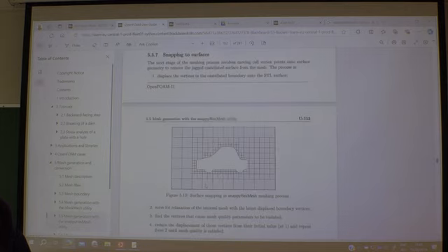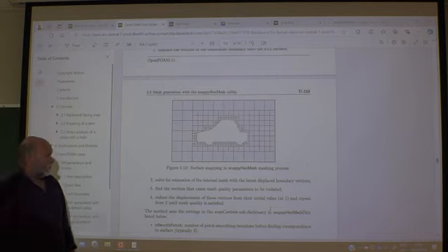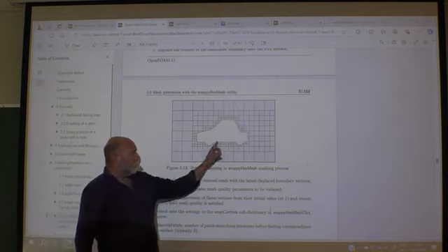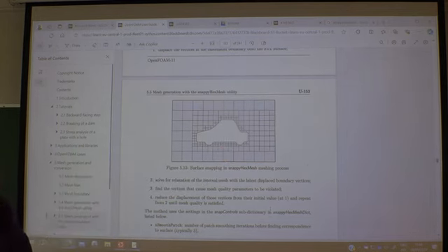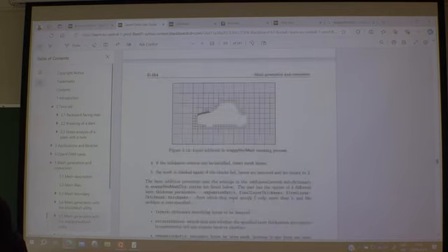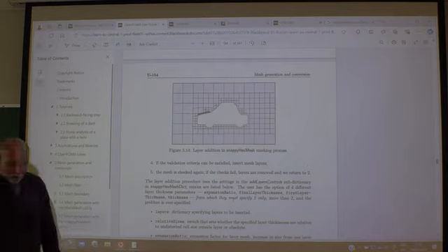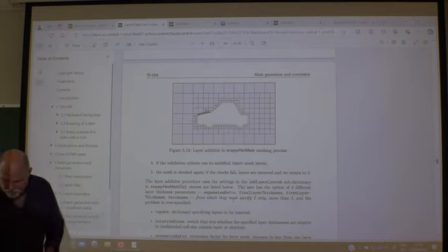So several steps have to be done before you end up with a fine, nice mesh, something like this. You can even add layers close to the surface here if you are interested in really resolving the boundary layers. So the recipe described here is quite short, and we need some better description.